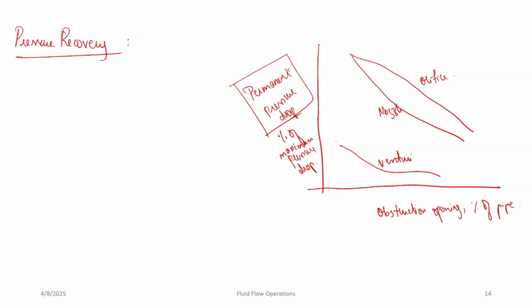After the constricted area, that is the converging section, the fluid is passed to the recovery section, which is the diverging section. Up to 80% of the differential pressure generated at the converging section or constricted area is recovered. Up to 80% recovery is possible.